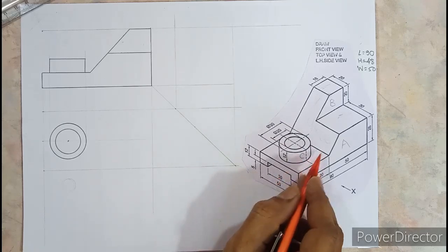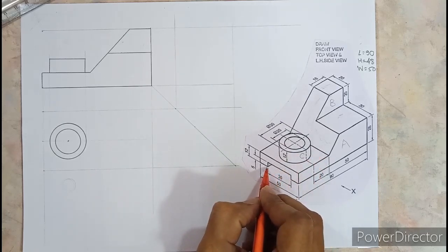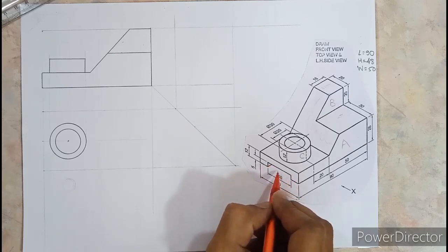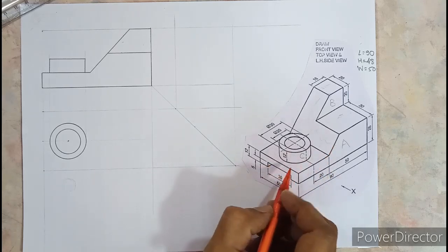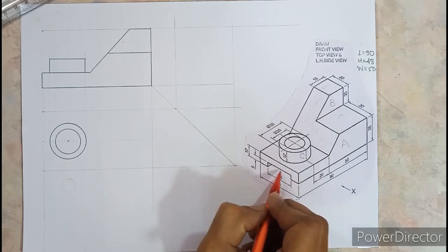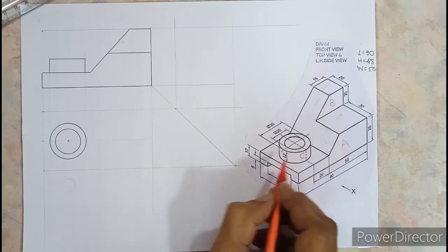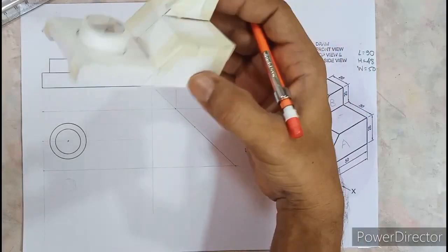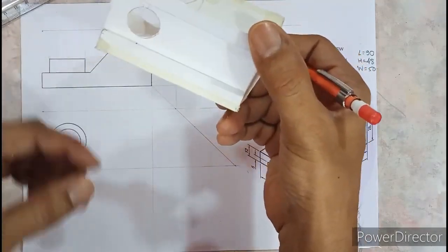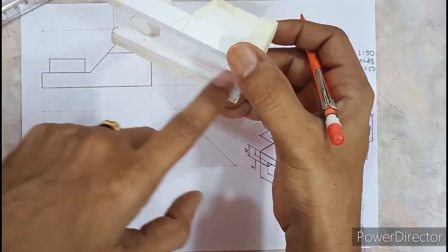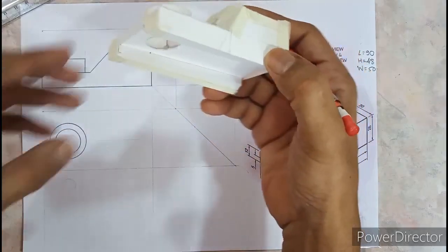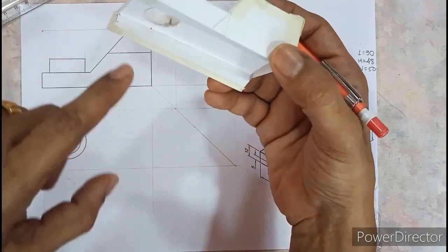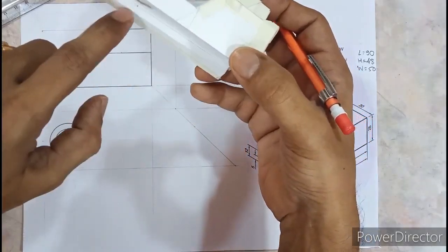And one very important thing I am going to discuss now is, whenever the depth of a cavity or the slot is not mentioned in the question, you have to assume it throughout. And when I say throughout, it means it should come out from the other side. So this height is how much? 5 millimeter. Even if you look at this object, see, there is a slot at the bottom. Can you see this slot? There is a slot over here. So the side you can see it correctly. Yeah, so you can see that there is a cutout over here. And that cutout is throughout.